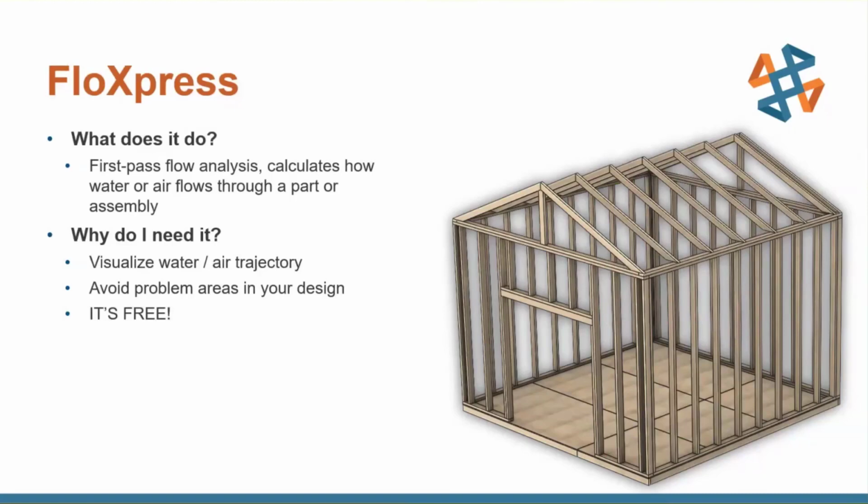So this is a first pass fluid flow. So you have actually computational fluid dynamics capabilities for simple conditions built right inside of SOLIDWORKS. So this is going to allow you to visualize either air or water flowing through your parts or assemblies. Does have some pretty noticeable limitations where we can have one inlet, one outlet. Can't have multiple fluids, multiple liquids or gases mixing or anything like that. Air or water, again, pretty basic to get an understanding about what's going on inside of the geometry.